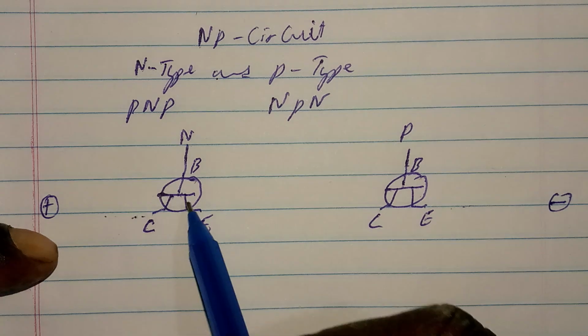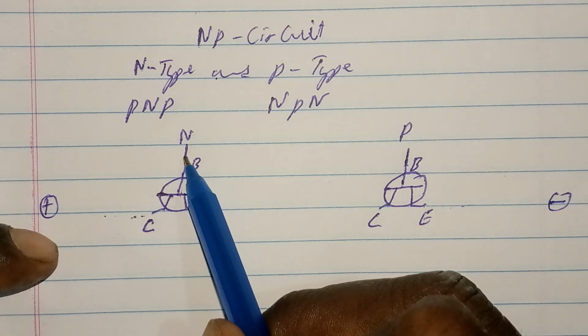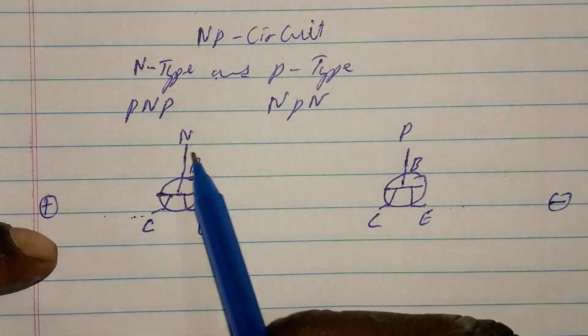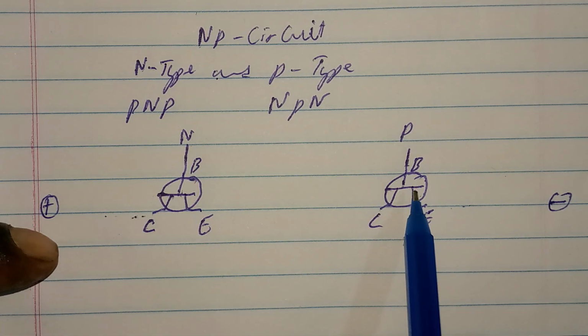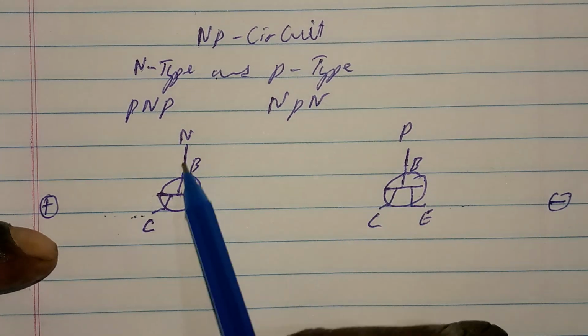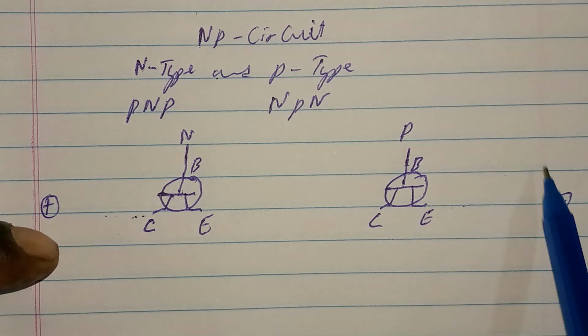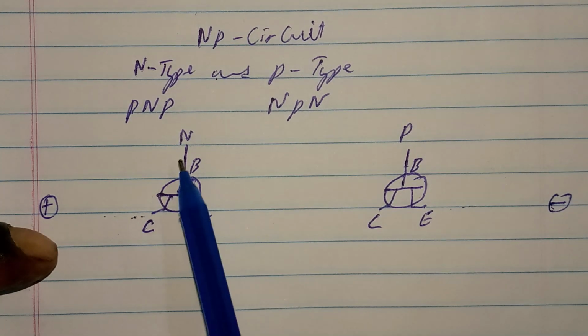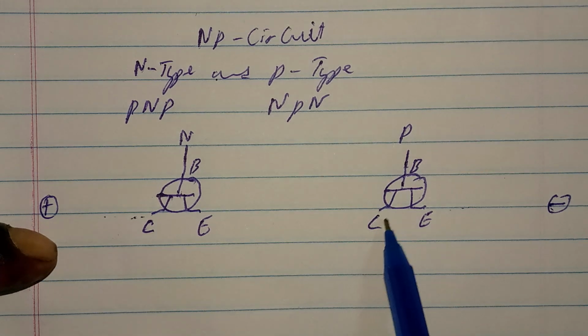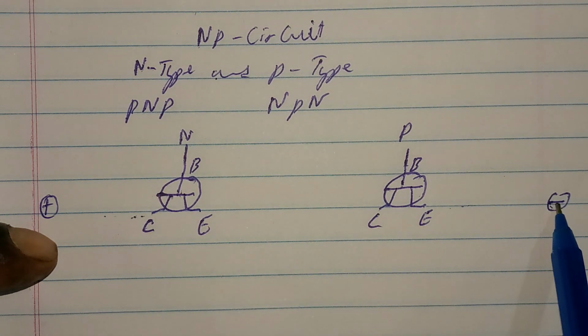Now, if you want to take a base voltage out of here to the negative, you already have another transistor here, because both transistors should be connected together, and this is not going to connect directly to the negative. It is going to pass through the other transistor, this P transistor, to the negative.